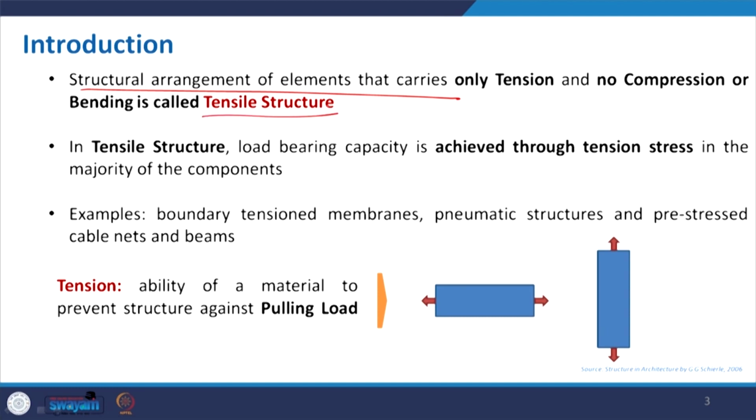Along with no compression there will be no bending as well, but there are some structures where a minor component may take compression too. The load bearing capacity is achieved through tension only, and the majority of the components of the structural arrangement are dealing with tensile stress.